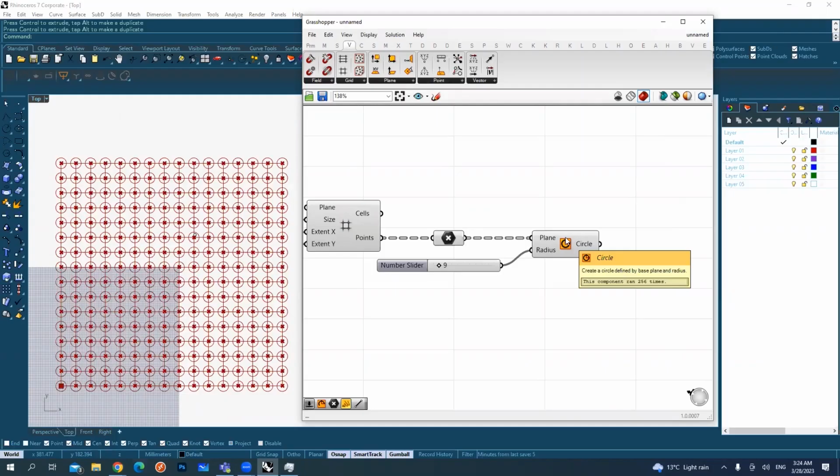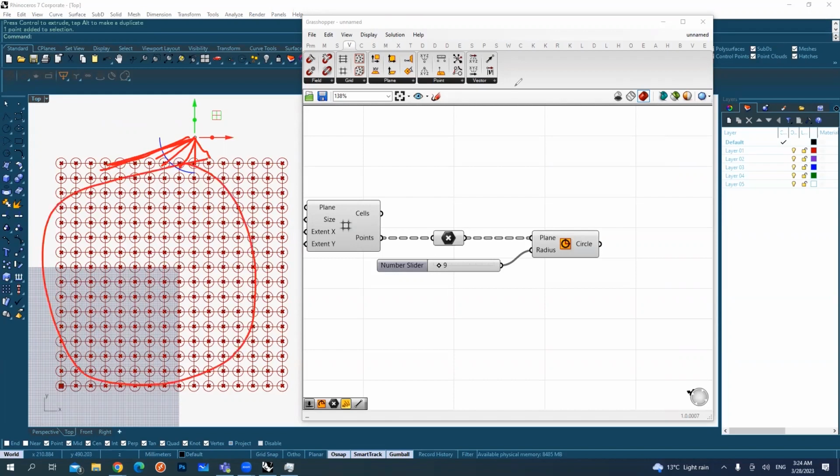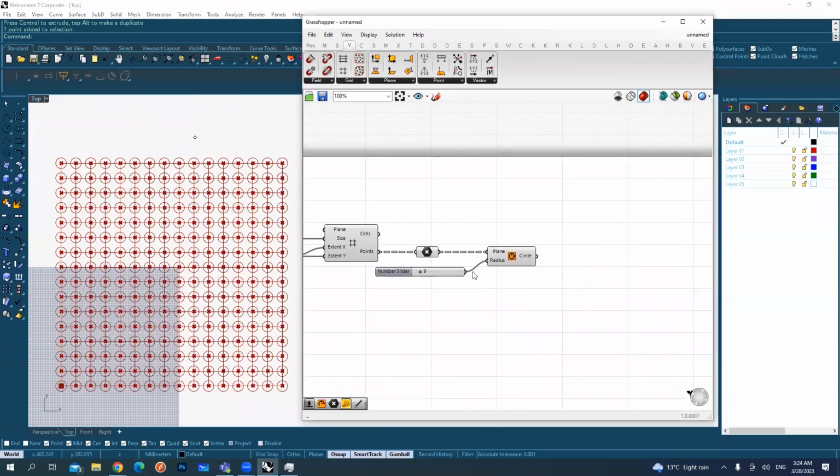The logic of it is to take this point, which is one point I created in Rhino, and to calculate the distances between this point and each single one of the other group of points. To do that, I will first call the point and link it between Rhino and Grasshopper.